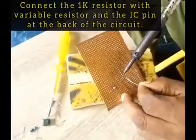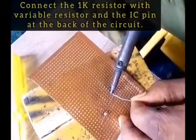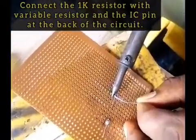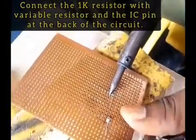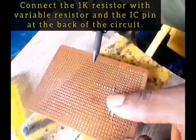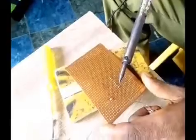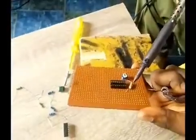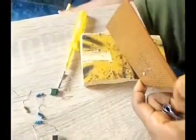Now connect our 1k resistor together to pin 16 of the IC socket like this. We have soldered 1k resistor together with pin 16 of the socket.